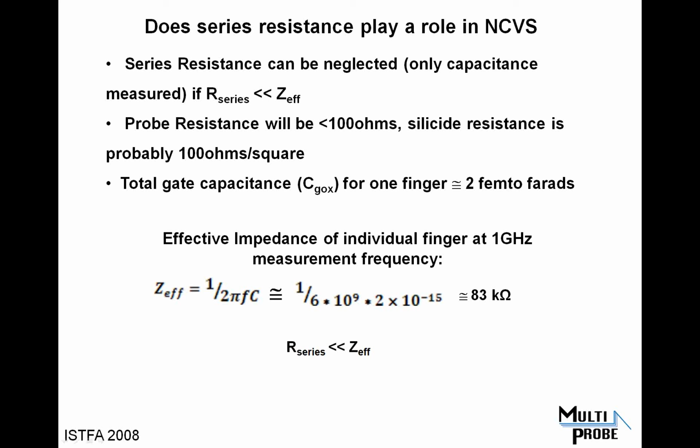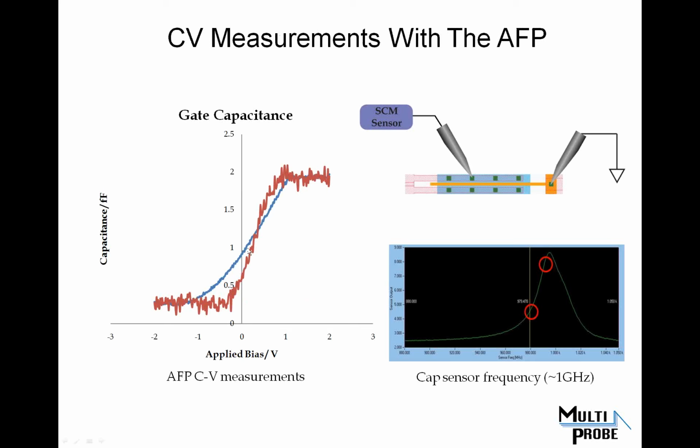And that's sort of contrary to the normal test structure measurements with long cables hooked up to boxes. What you do have to worry about, however, is how you operate the sensor. So we've done a little diagram of the capacitance sensor and some probes and shown 2 curves. One of them, the red curve, is fairly noisy, as you'll see, but it has a fairly flat top and flat bottom and a fairly sharp transition.